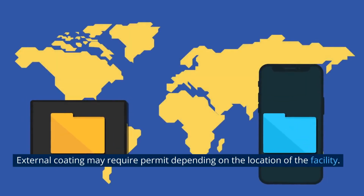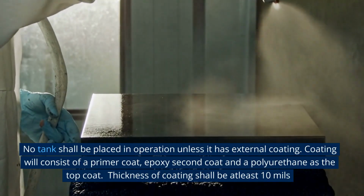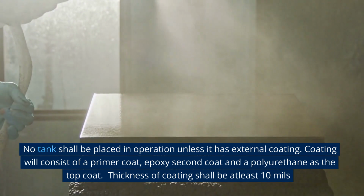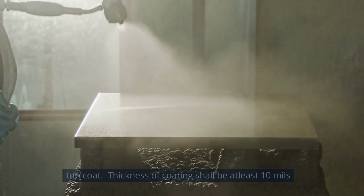External coating may require a permit depending on the location of the facility. No tank shall be placed in operation unless it has external coating. Coating will consist of a primer coat, epoxy second coat and a polyurethane top coat. Thickness of coating shall be at least 10 mils.